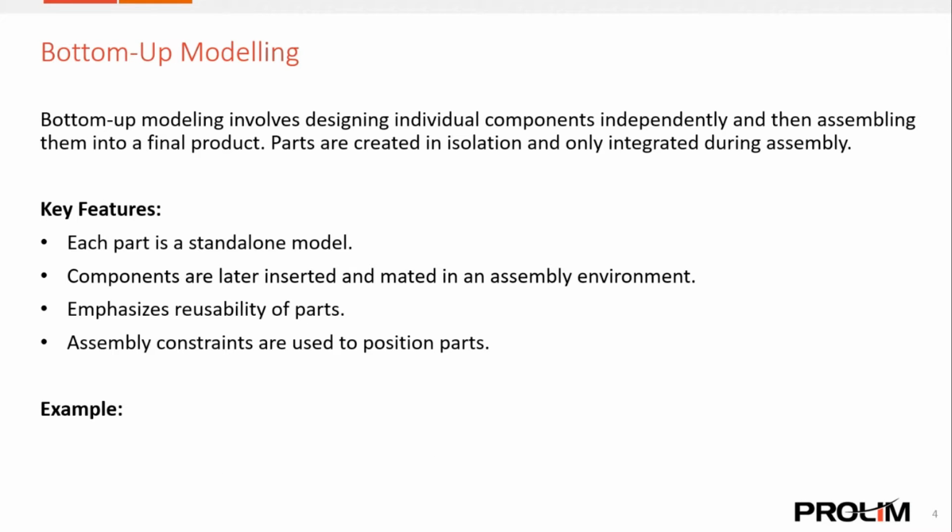Now, bottom-up modeling involves designing individual components independently and then putting them into a final product. Parts are created in isolation and only integrated during assembly. The key feature is that each part is a standalone model, and components are later inserted and mated in an assembly environment, which allows you to emphasize the reusability of that part.